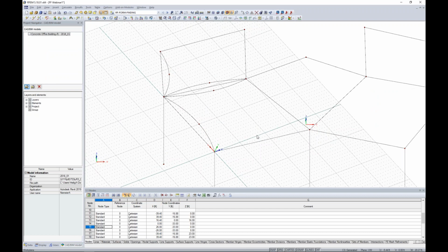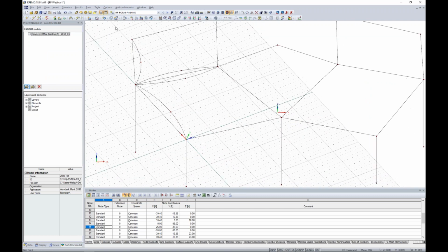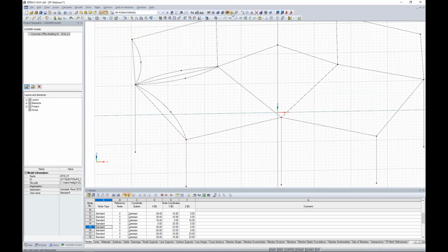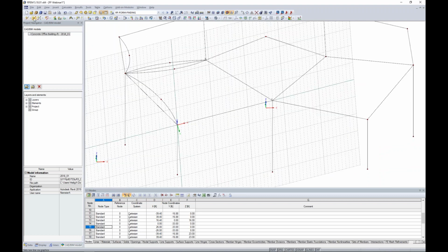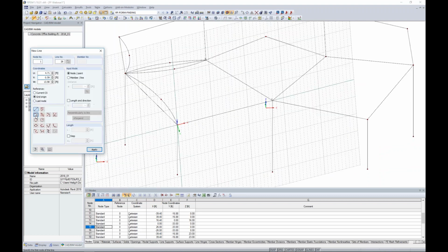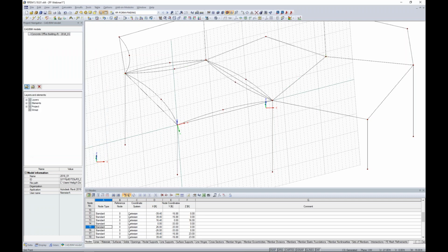We need to lastly do so over here. So we click this option up in our toolbar for a user-defined grid, click our 3 new points, and now we have the specified angle is given. We go back to draw a new line element as an arc with 3 nodes and continue on with this process for our additional cable elements. And one more time for our 3rd cell.